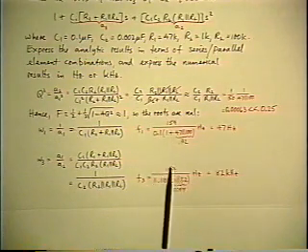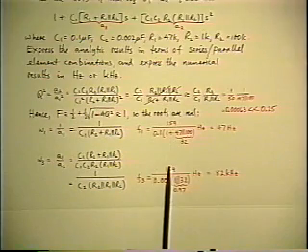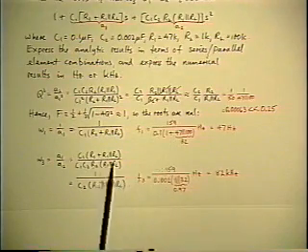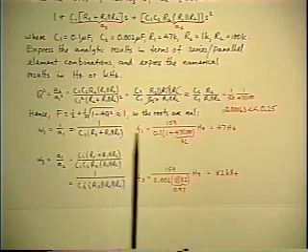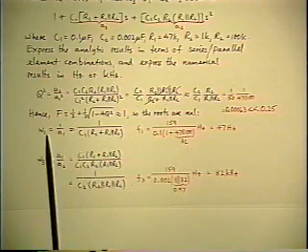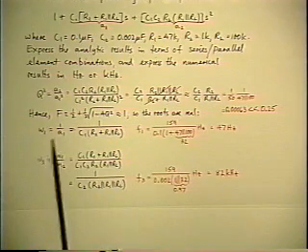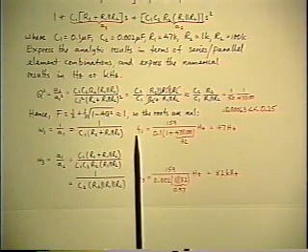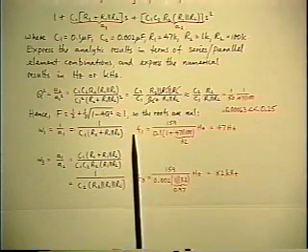Another little trick that I'm sure you've all discovered long ago. When you change from symbols to numbers to do with frequencies, the formulas give frequencies in radians per second, and the numbers you want to come out in hertz, and there's a 2 pi in between.